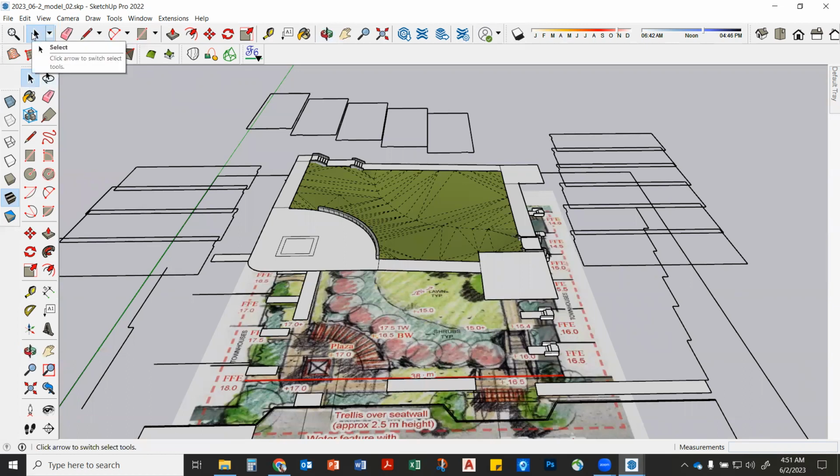But you can if I did a save as of that old model. If I do model to model, like exact model, this one's a little bit different because I shifted the base plane. You can actually just drop things from model to model, edit, paste in place, and it'll drop right where you need it to. But for this one, we're just going to do Control V, right? Or edit, paste, whatever you want to do. I always use shortcuts, Control V, right? So there it is.